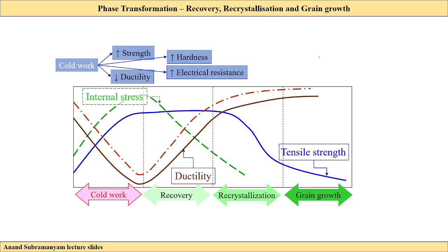and decrease the areal dimension, that means if I decrease the thickness to 2 by 2, the length will increase. That is what happens in rolling, right? We try to decrease the areal dimension, so the other length dimension will increase, because the volume has to be conserved finally. So that is what happens.